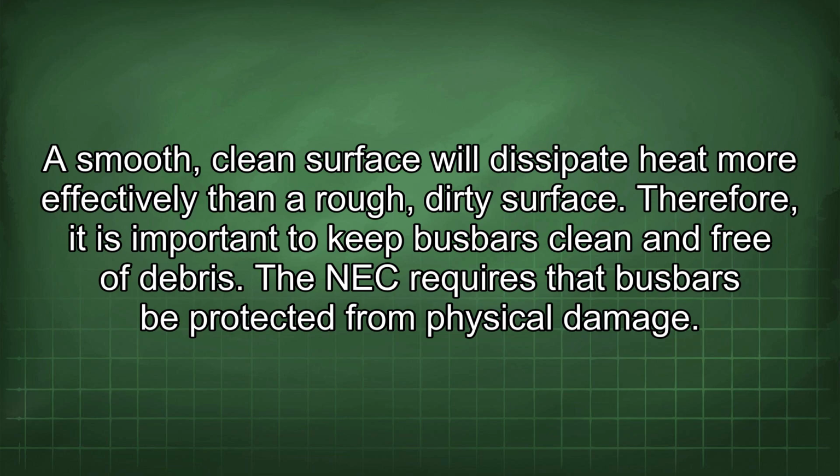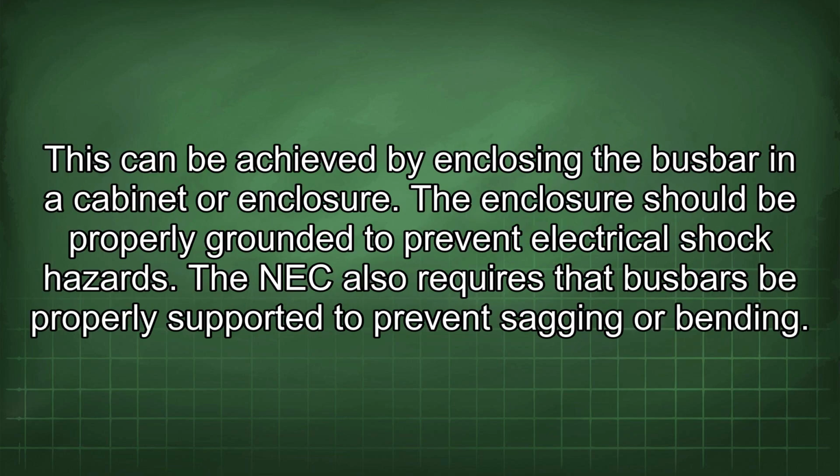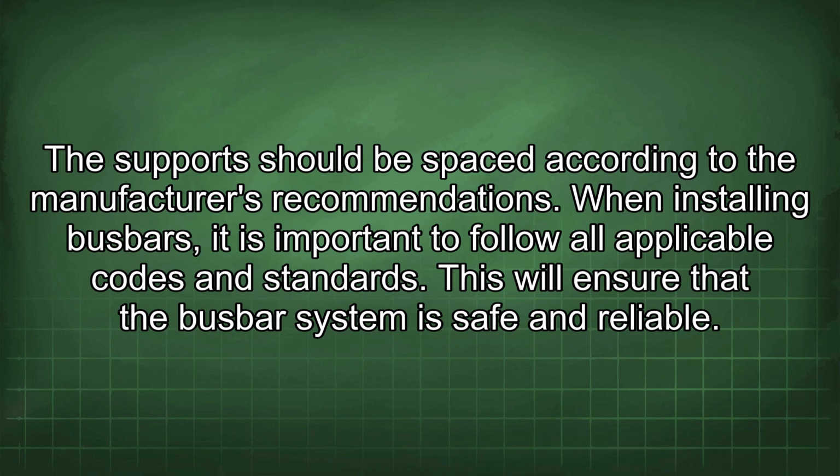The NEC requires that busbars be protected from physical damage. This can be achieved by enclosing the busbar in a cabinet or enclosure. The enclosure should be properly grounded to prevent electrical shock hazards. The NEC also requires that busbars be properly supported to prevent sagging or bending. The support should be spaced according to the manufacturer's recommendations.